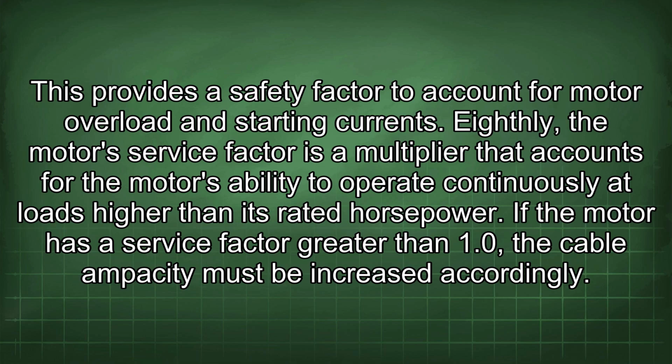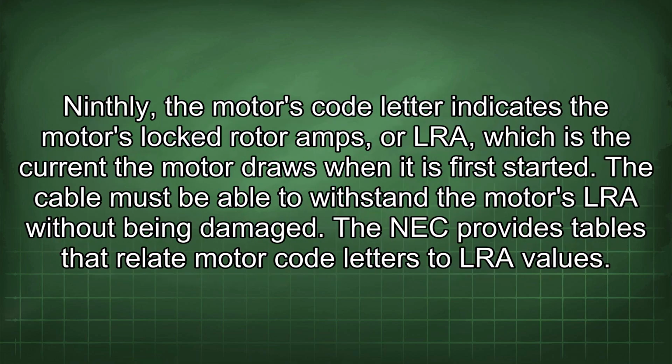Eighthly, the motor's service factor is a multiplier that accounts for the motor's ability to operate continuously at loads higher than its rated horsepower. If the motor has a service factor greater than 1.0, the cable ampacity must be increased accordingly. Ninthly, the motor's code letter indicates the motor's locked rotor amps, or LRA, which is the current the motor